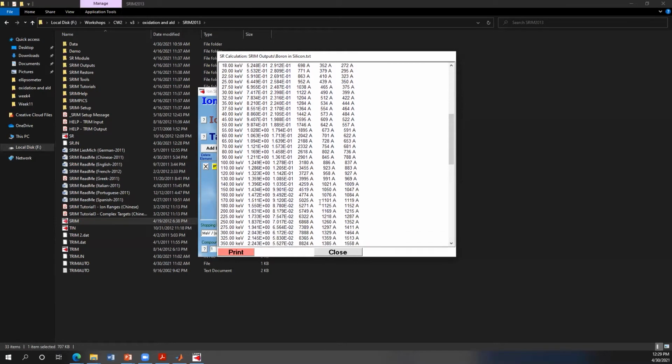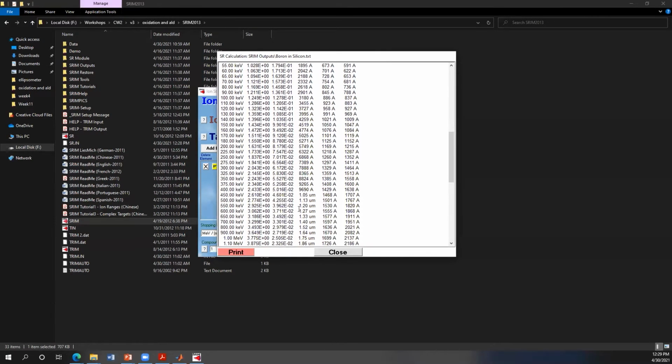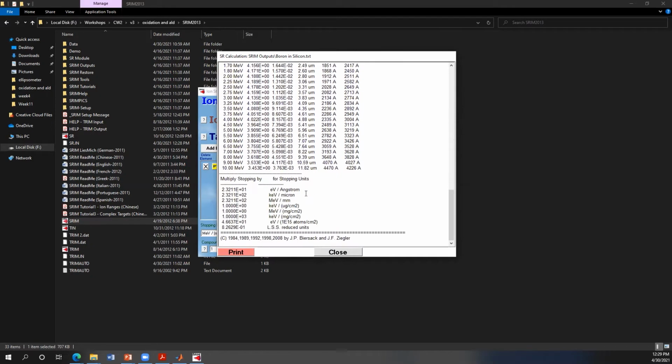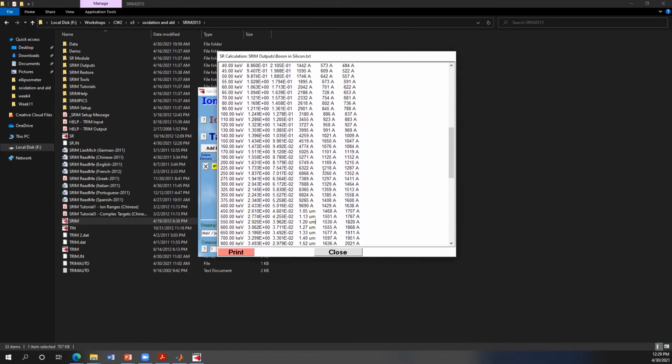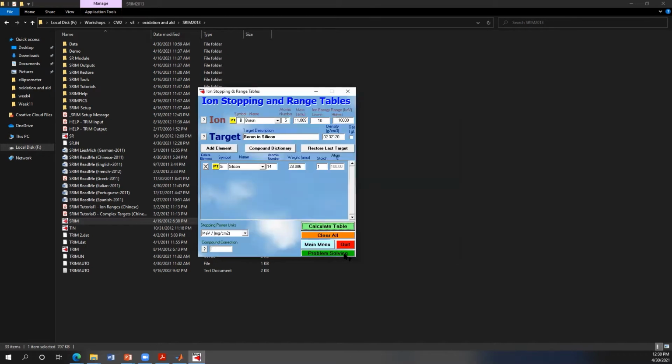So if I increase the energy, look what's happening. It's increasing accordingly. Say if I increase it up to 450 kilo electron volts, really high energy, it's relativistic right now. I think it's going to implant very deep. So it's going to be like 1 micron already. So that's as far as we go, and we can go even deeper with increasing energy. And then there will also be the deviation, of course. You can think of straggle in that sense as well.